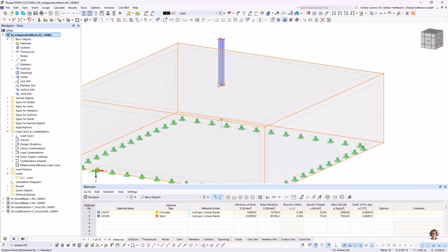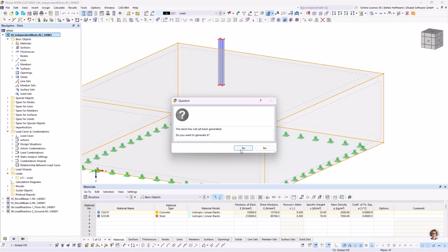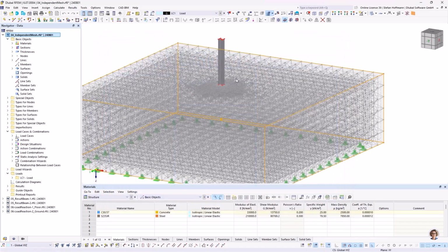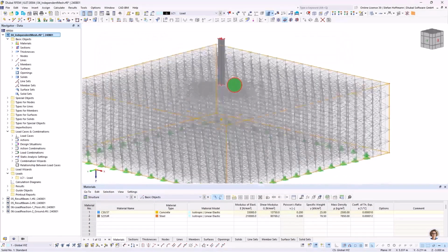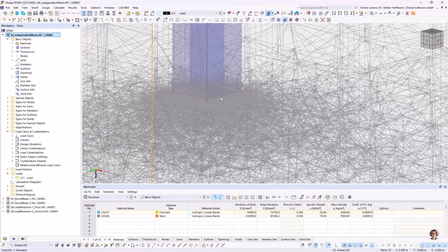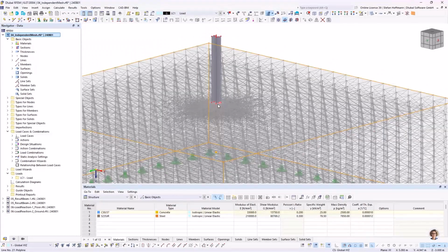And if you then have a fine mesh connecting to the solid body, it needs to be connected at FE mesh nodes. If we generate the mesh without any extra setting, then the mesh will most likely have such a fine representation, because the fine mesh of the surfaces needs to be directly connected to the solid in the ground.